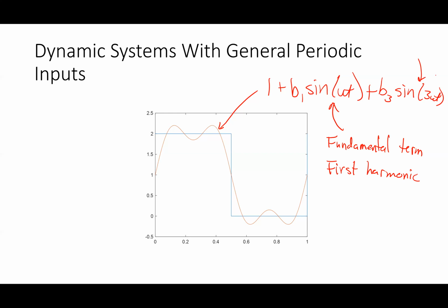This stuff happens all the time. In the real world, we have square waves. Or if I look at the wall outlet, I'll see that I have 60 hertz plus 180 hertz. So the voltage at the wall is 60 hertz. What's 180 hertz? Which harmonic would that be? The third. So these things happen in the real world, that I get those sorts of waveforms.